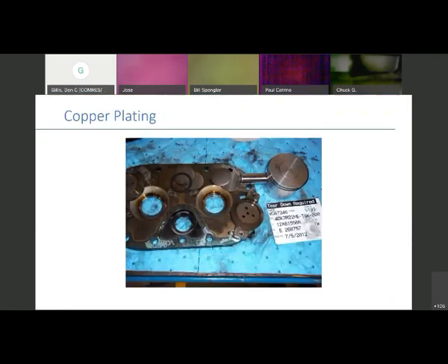Don, yeah. We do have an answer. Paul Catrino posted out there, maybe you need double risers, and Ed Sethens validated, yes, use a double riser on systems with capacity control, either variable speed or digital. That is great. I think Ed even touched on that the other day at full capacity. Very good. Yes, any form of capacity control that has lower velocity, especially if the capacity drops below 40%. Okay, thank you, Dave Dowen, Paul Catrino, and Ed Sethens. Thank you, guys. Appreciate it very much.